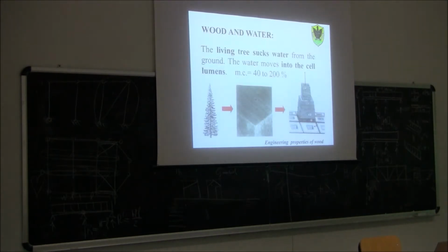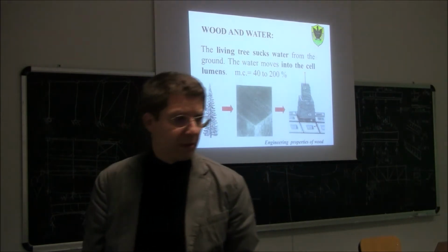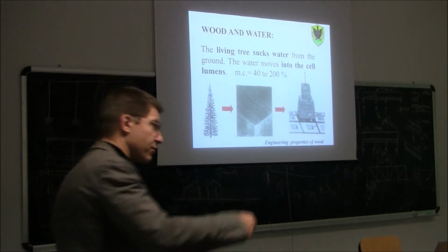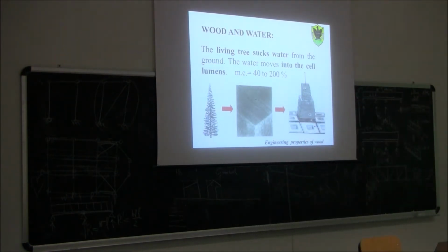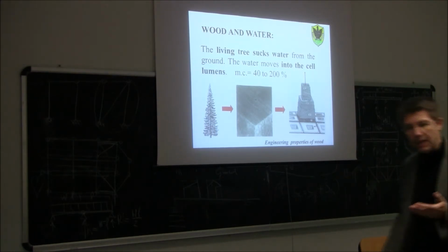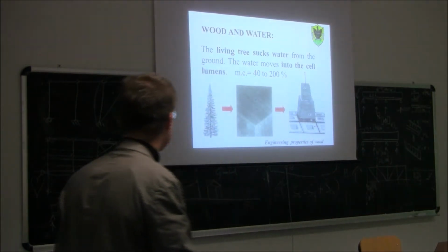So this is the instrument. Basically, on the building side, when you have to measure the moisture content, you use this instrument. Even if you have to buy, for example, some parquet for your house, it's always a good idea to measure the moisture content of your wood with this instrument. Because, as I said before, it's very important that the wood has been seasoned, so the moisture content is low once you get your wood delivered. Otherwise, if the moisture content is high, you can have a number of potential problems.